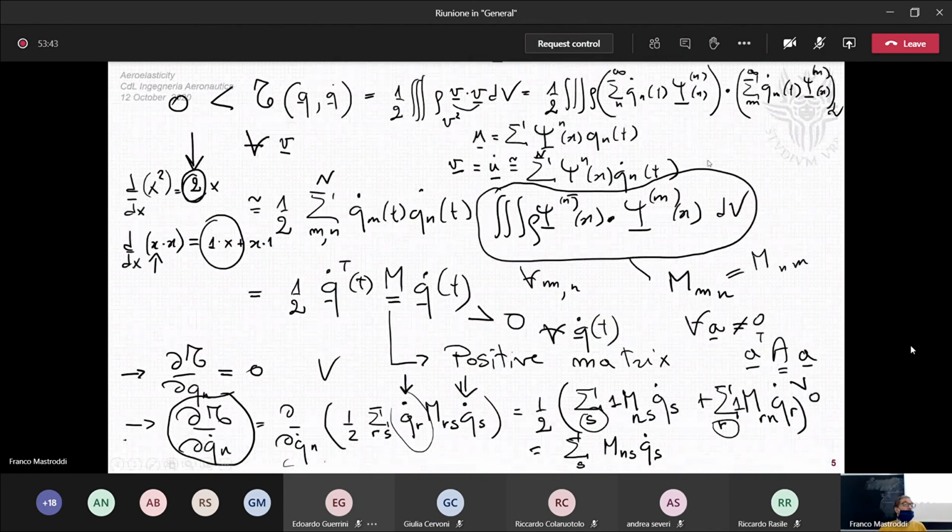Tomorrow we obtain the last part of the equation, demonstrating that any kind of linear elastic body can be represented by this equation. And in particular, if you use the shape function as done in the finite element approach, the corresponding meaning of the Lagrange variable is the displacement at the node point. And this is an advantage from an engineering point of view.